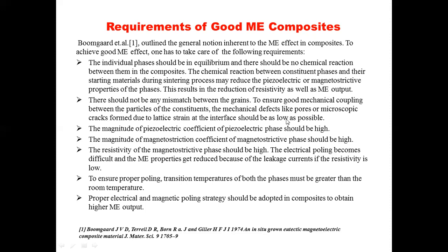These pores and microscopic cracks formed in the composite material will definitely hinder the properties of the ME composites. So care should be taken that the porosity level is at a minimum, and we have to maintain a high density and a high purity of the materials. So that is very, very important.